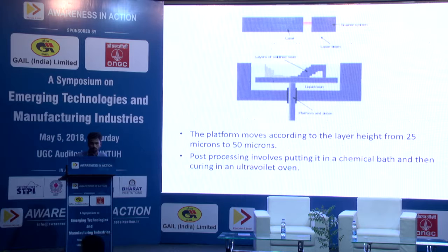So once it is cooled, there is something called a support structure. When I'm saying subtractive manufacturing and additive manufacturing, the difference is that in additive manufacturing, if I'm printing my structure in this manner, there is no medium over here. So it is called a support structure. It'll start printing from the first layer itself until here, and this will be my actual part. After the complete printing is done, I remove the support structure. The density will be lesser, so it is easier to remove.